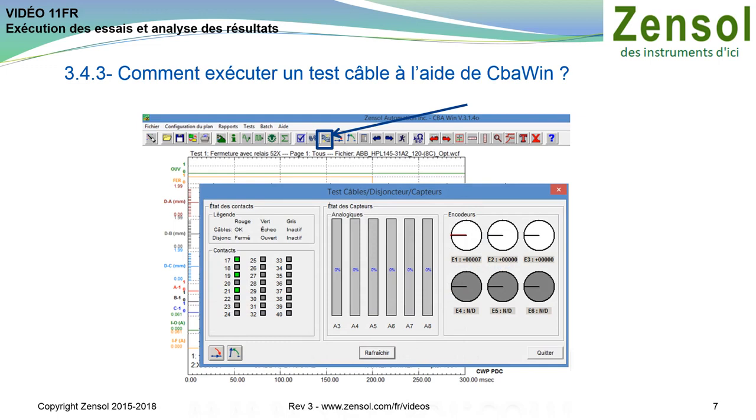The middle section checks analog inputs and connected resistive sensors. If it's white, the input is active. If it's gray, it's inactive. Ideally, resistive sensors should be around 50% to prevent them from dropping to 0. In this case, the analog inputs are grayed out and not activated. The right-hand section shows the status of the optical encoders. Here too, white is active, gray is inactive. In this example, only the first 3 optical encoder inputs are active.